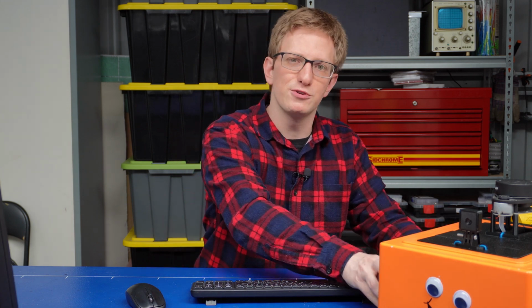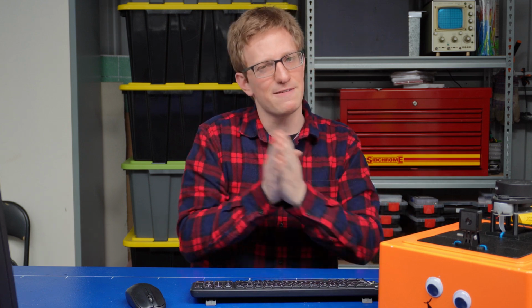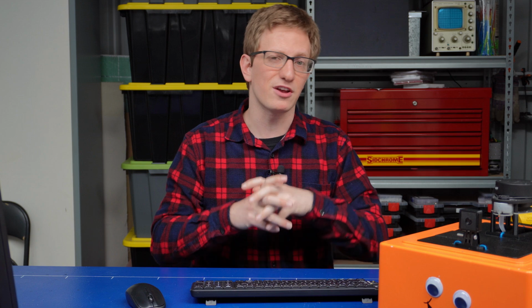For this tutorial though, we'll be using the one I wrote, and it's called Diff Drive Arduino. And all it does is it exposes those 2 command interfaces, that's the velocity of the left wheel and the right wheel, and it controls them using those same M and E serial commands that I showed back in the motor control demo video. It also exposes the 4 state interfaces, so that's the position and the velocity of each wheel, and then the control is all going to happen in the same diff drive controller that we showed in the last video. That's all handled by ROS2 control. Now, to actually install my hardware interface, it'd be nice to be able to just type sudo apt install diff drive Arduino.